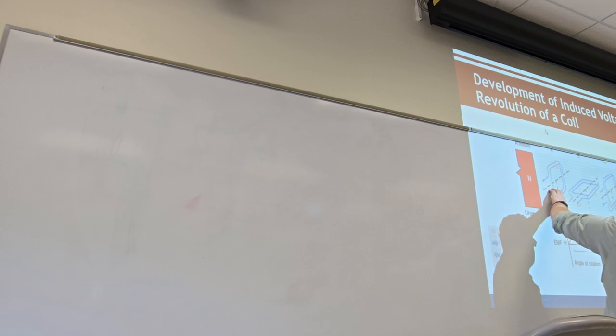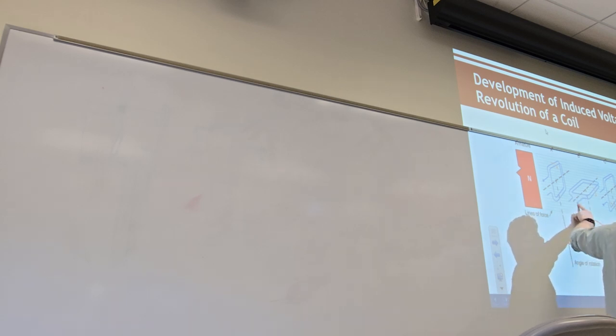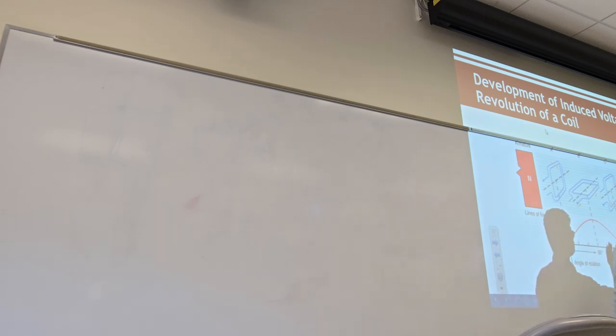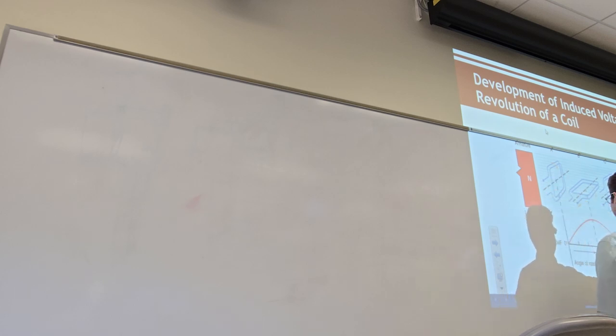It's practically invisible. But when we are perfectly perpendicular to that signal, we are in a good position to receive it. We get a large amount of force induced into that wire, like an EMF. We keep turning it. We're in the same position, essentially the same topography, the same layout of wire as we were in the original situation. We're back to 0. And something interesting happens here. When we turn it all the way the other way, effectively 270 degrees, we have a negative voltage.